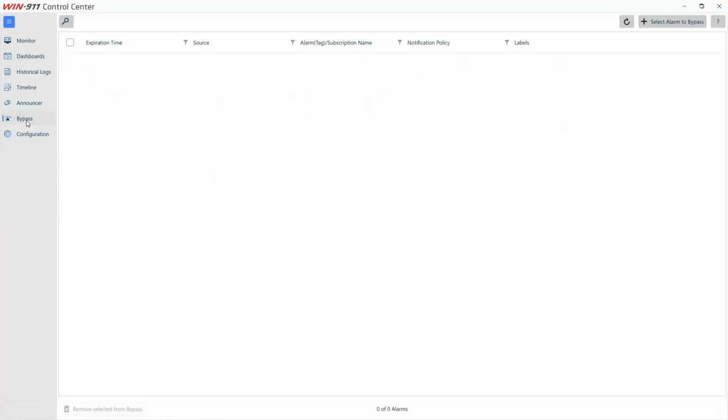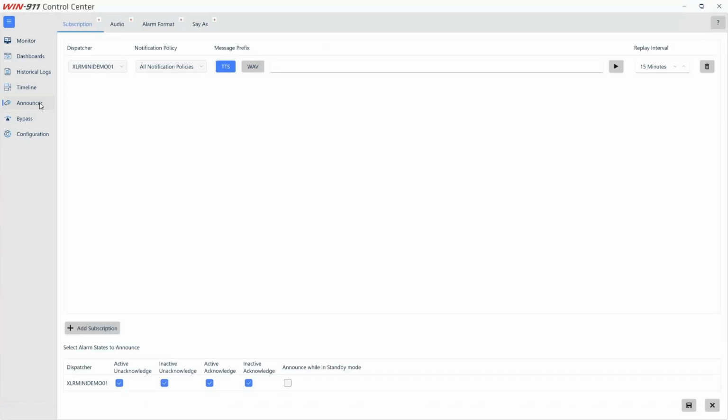So say you're doing maintenance on some equipment that's going to be disconnected or shut off, and that's going to create a bunch of nuisance alarm activity that doesn't represent a real abnormal condition. You can define that you want to bypass alarms for certain periods of time, say while planned downtime or maintenance is happening. You can also program this thing to announce alarms over a speaker, right?